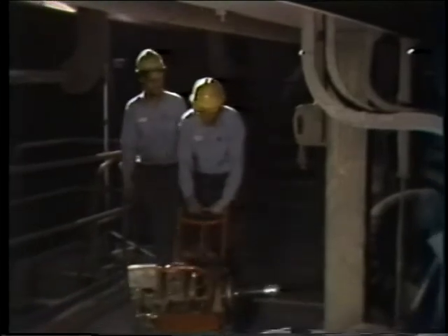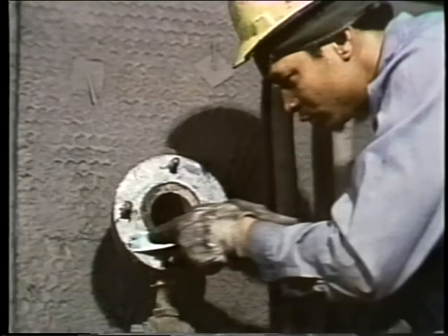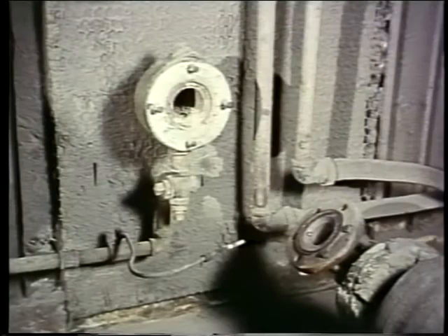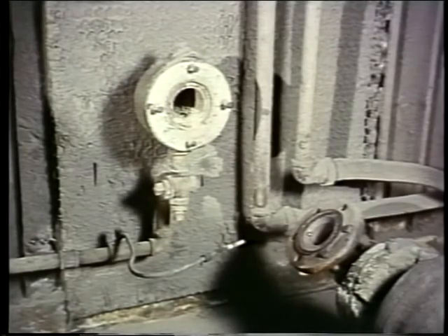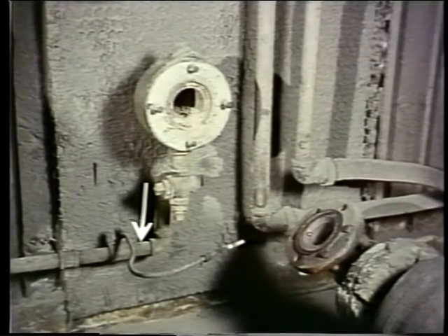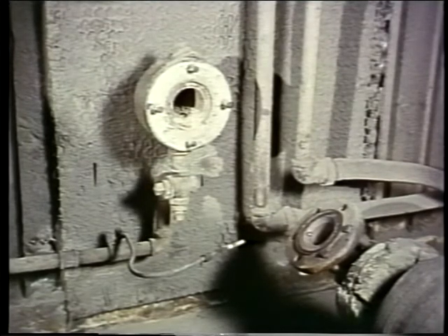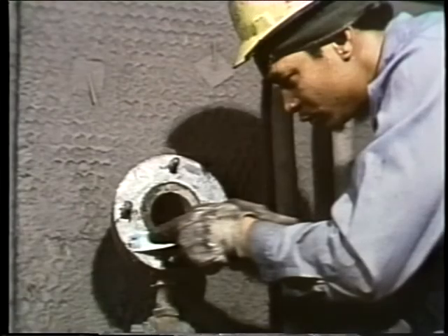Before the soot blower is put back into place, its location on the boiler should be prepared by cleaning mounting surfaces where gaskets must seal. This particular installation has a sort of box on the boiler wall that has a purge air system to keep it clean. Air under pressure is fed into this wall box to blow dust and soot away to keep it from fouling the element where it goes into the boiler. Nonetheless, the wall box itself needs to be cleaned before the soot blower is reinstalled.